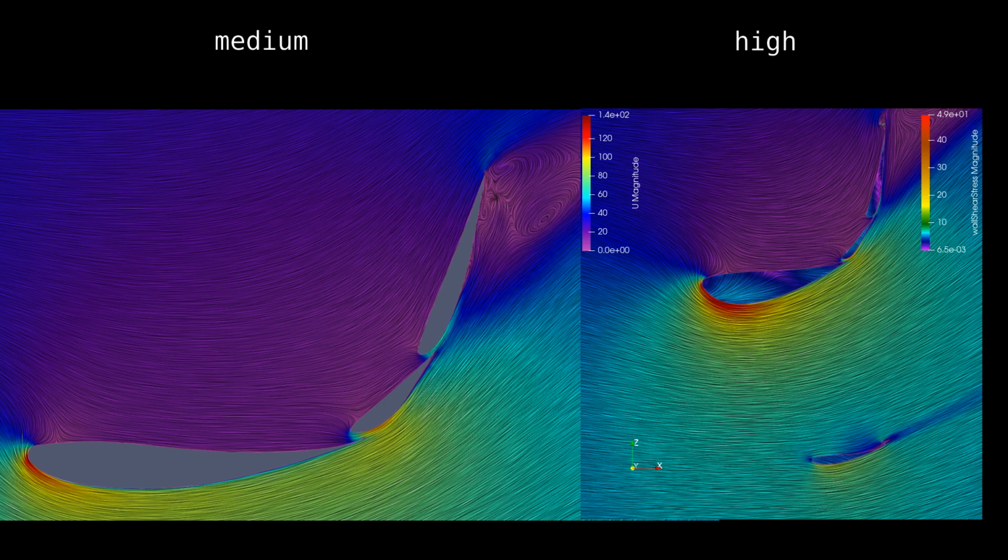I probably would have been lost for longer if I hadn't read John Barnard's biography, where he stated the most important part of a high downforce triple element wing to work is the second element. If the second element is attached, most of the work is done.